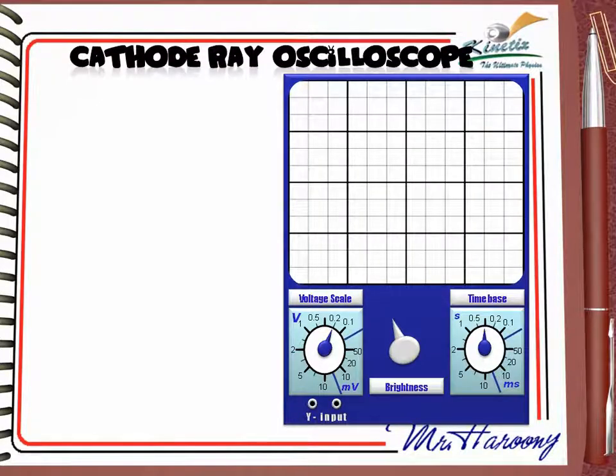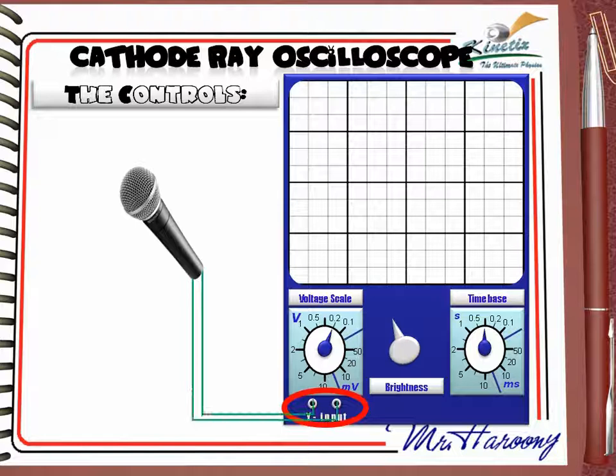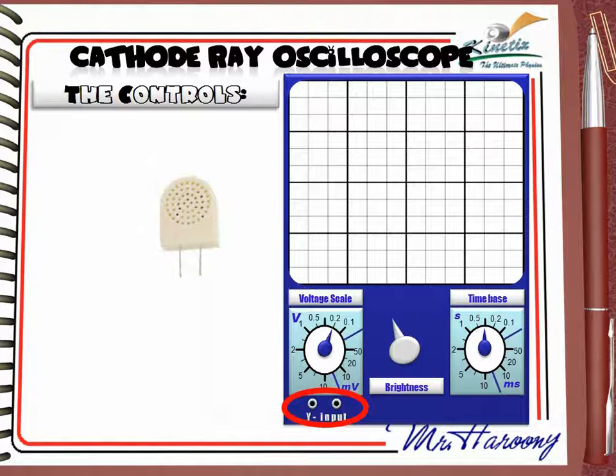In this part, we will study the main controlling buttons of the CRO. Before that, we must know that the signal or the voltage to be studied must be applied to the Y input. For example, to draw the sound waveform, the microphone output is connected to the Y input of the CRO as shown. Similarly, to study the change in humidity, the humidity sensor is applied to the Y input.